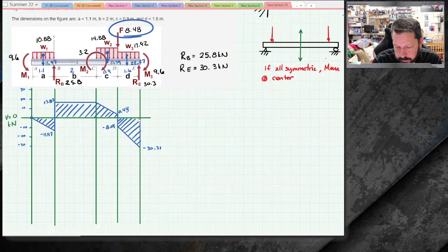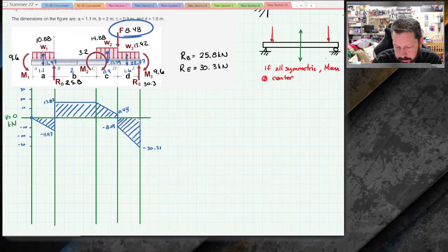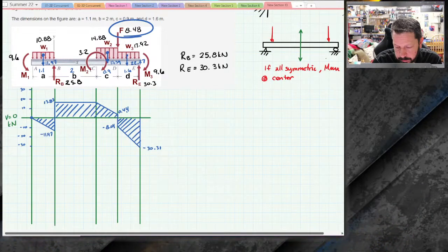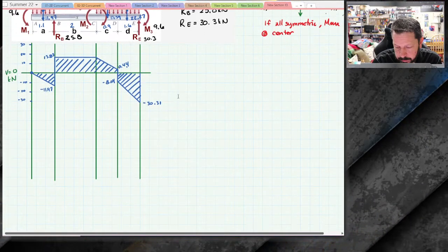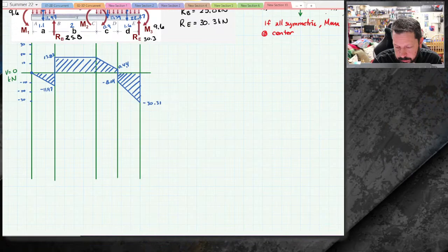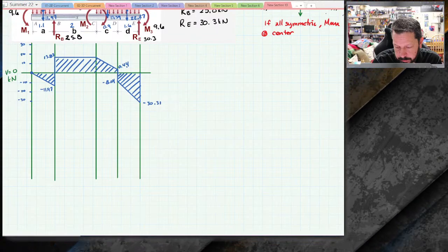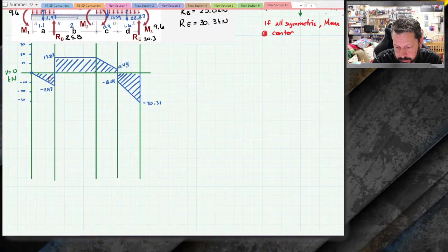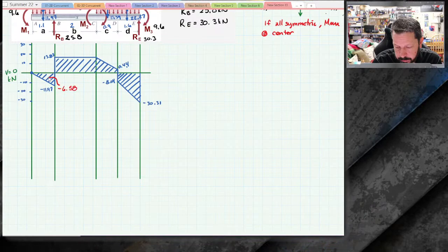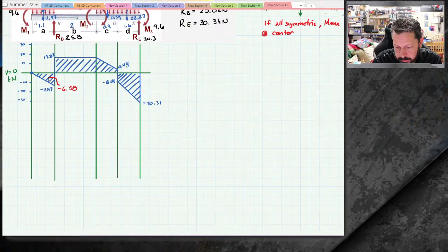Now we want to do the bending moment diagram. This one, remember, most of it comes by integrating the shear diagram. So this one does have all these concentrated moments, though, that we'll have to take into account. But let's go ahead and integrate the shear diagram. So I've got 11.97 times, that's the height of this first triangle, times a base of 1.1 divided by 2, because it's a triangle, negative 6.58. Lots of rounding. The next one is 13.83 high plus 2 wide, and it's a rectangle.